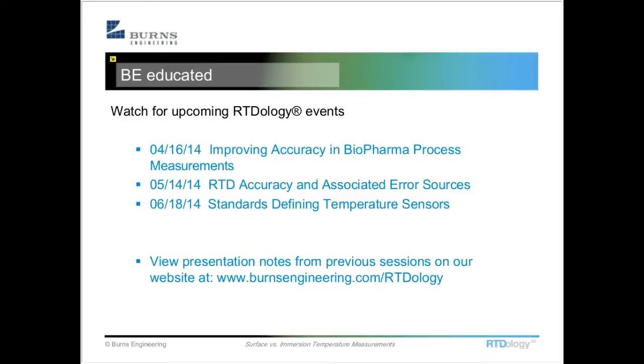And that's based off of a manufacturer's resistance tolerances for those lead wires, because in a 3-wire system, the accuracy of that lead compensation depends on each one of those conductors having exactly the same resistance. And of course, in the real world, they do not. So you're going to get a little bit of an error associated with that.